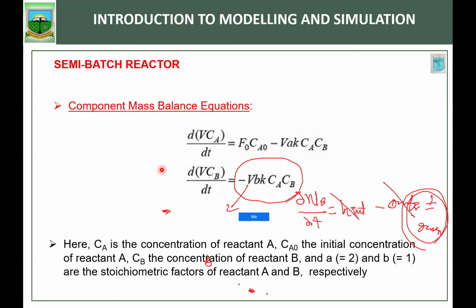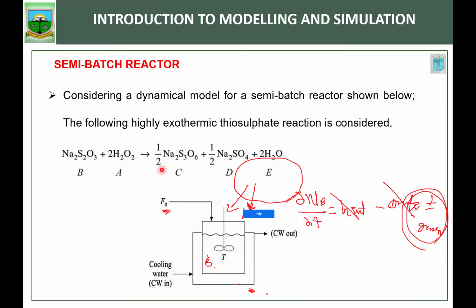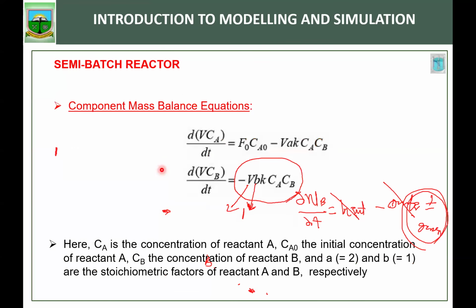This is the volume of the reactor. This is the reaction coefficient of B in the reaction. Then it is 1, right? In the reaction, B is 1. You can see that B is 1 here. The coefficient here is 1. So it's fine. Then we have the K, then we have CA based on the order. Now, if we have the K, we can change this to the Arrhenius equation, right?